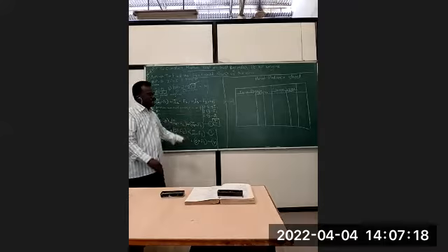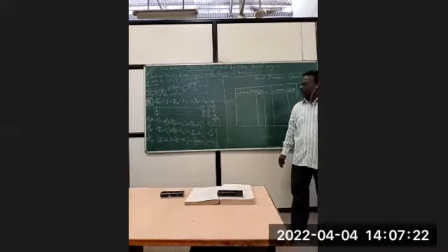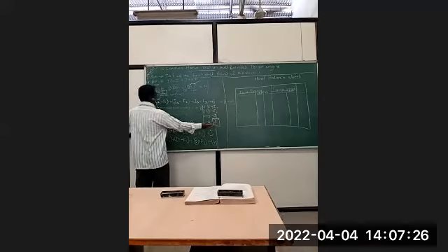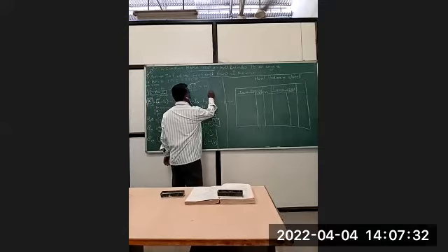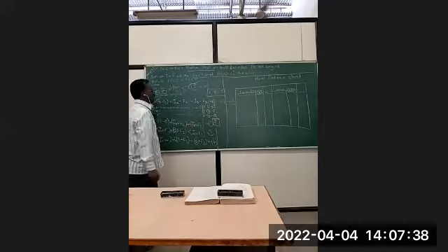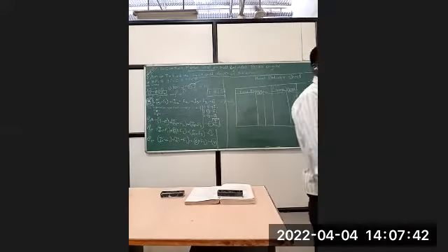So remember that this particular test has to be taken with a constant speed. And finally, we will find out I1 plus I2 plus I3 is equal to I, and we have now B. So this I minus this particular B, that will give you F. So I minus B is equal to F. So this value minus this value will give you the final frictional power of the engine.